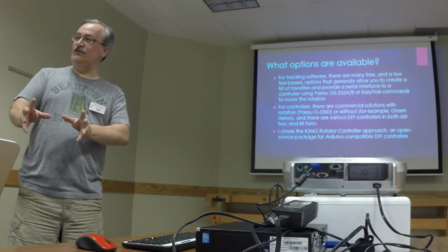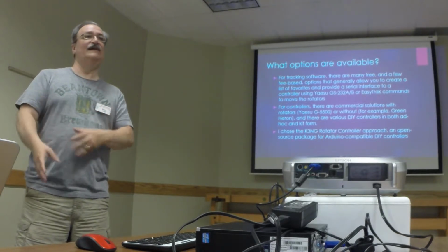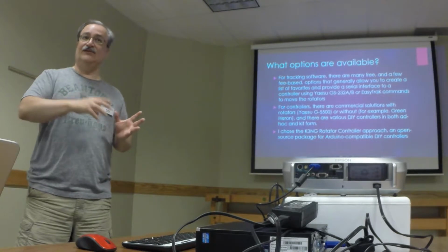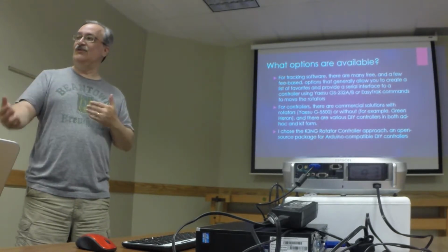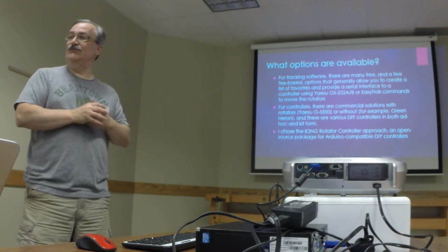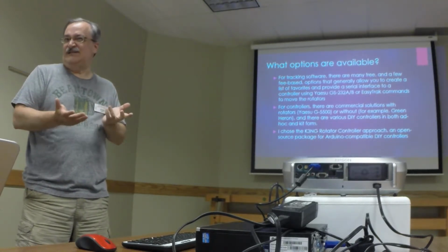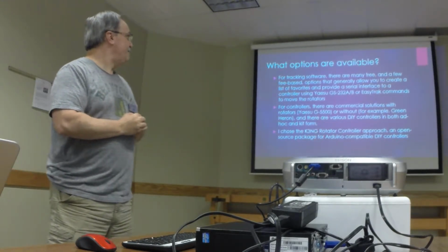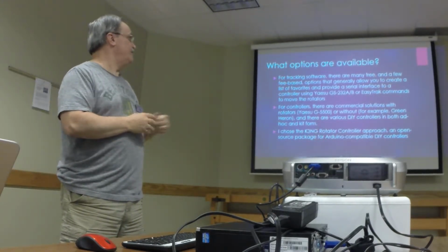So they're a control unit to the PC, a device. PC's the host, and they're trying to, over typically 9600 BPS serial, communicate these ASCII character-based commands to the controller. So it's a very simplistic approach as far as the interface goes, and very reliable.